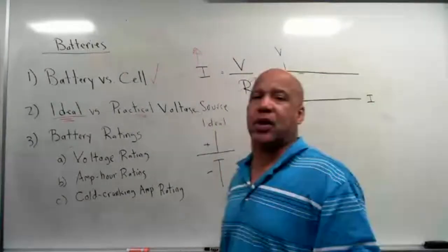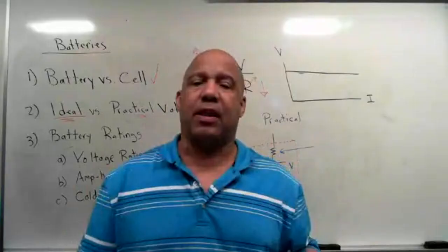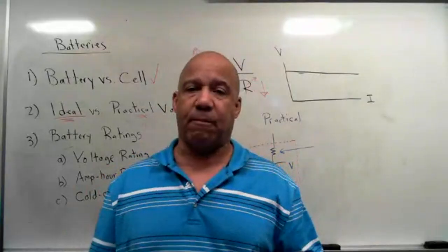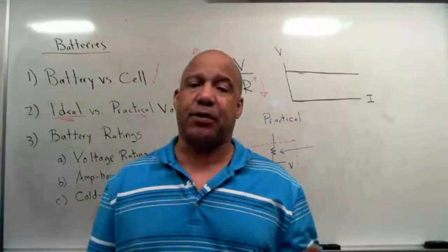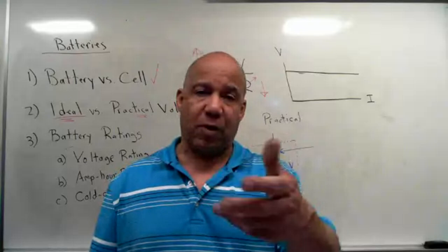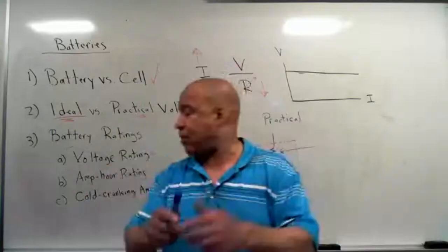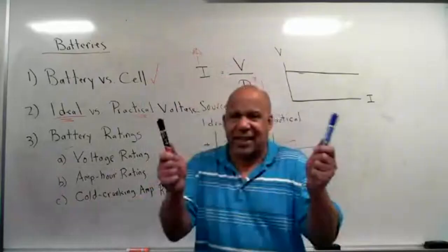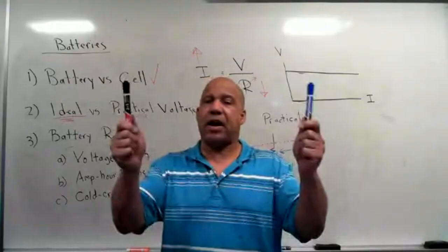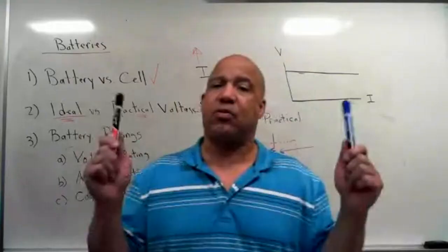I think you're right. So guys, don't do this right now, but later on, you all have meters. I'm assuming you all have a digital multimeter. When you get time, take your digital multimeter, turn it to ohms. From watching that video, you know how to do that. Take the leads and squeeze them as tight as you can and measure the resistance. If you hold it in your hands and squeeze those leads and look at the resistance, you're measuring the resistance of what?